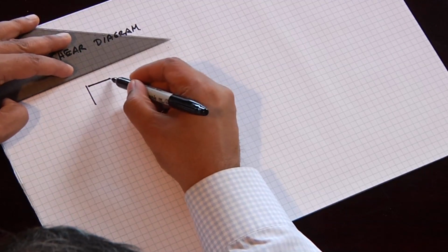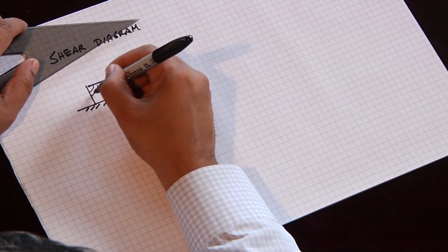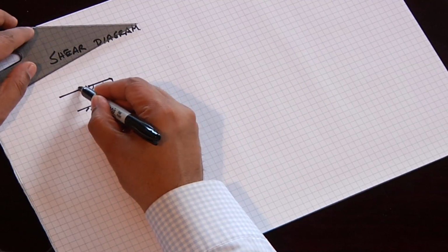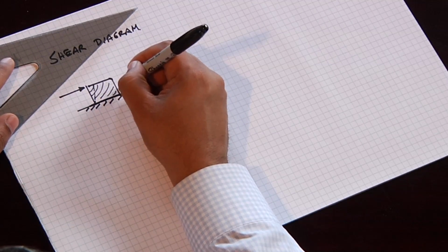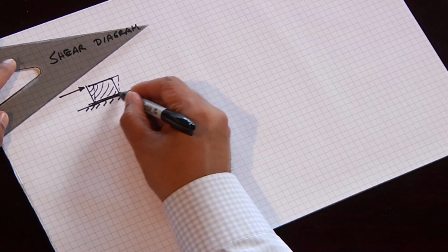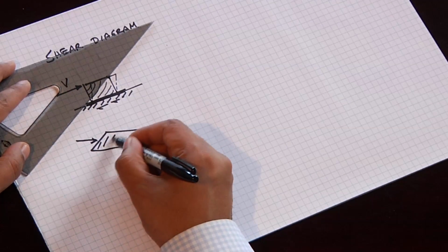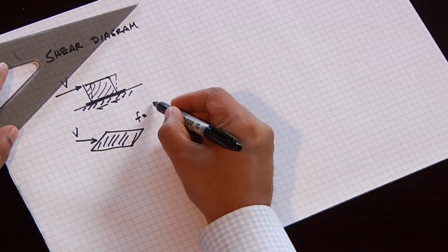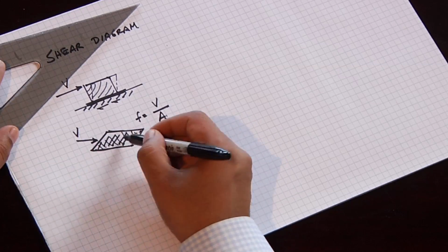So if we take the example of a block, just take a block of wood, for example, sitting on a table, and here's the grain of the wood, and I apply a force, and we'll say for right now that this is glued to the table. This block is undergoing a shear force, and that glue that holds that block to the table is undergoing a shear stress. So shear is a force that's applied to a cross-sectional area, and the stress is defined as that force divided by that area. And so the relationship between a shear force and a cross-section is that the two are in the same plane.